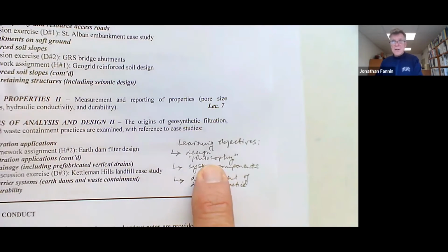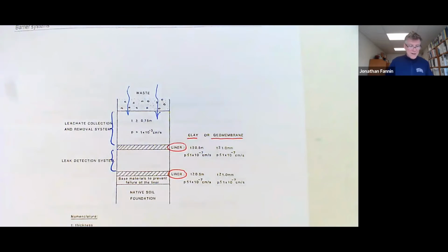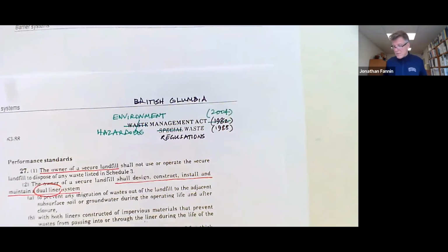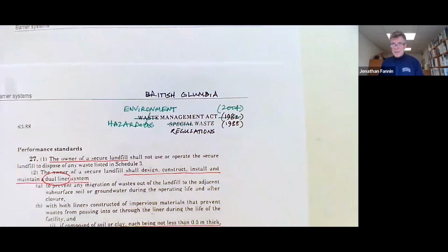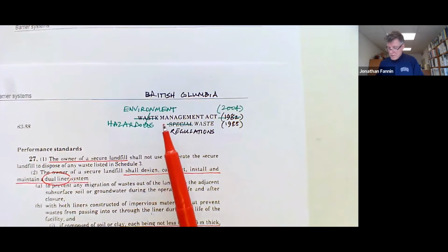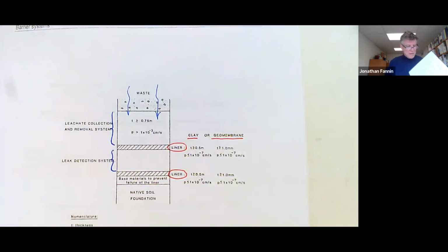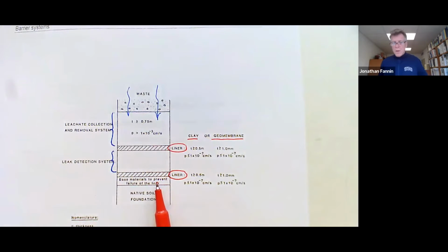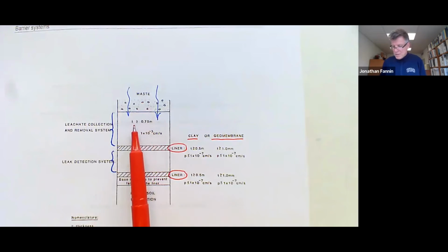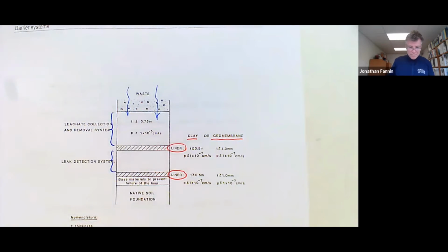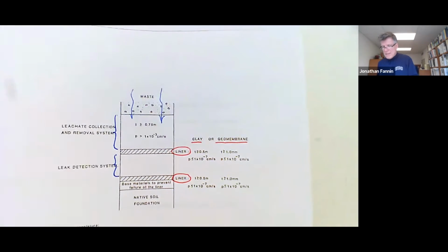There's a philosophy in terms of the objectives and the design philosophy, depending on the nature, depending on how aggressive or how hazardous, and there are criteria for what constitutes hazardous liquid by its biochemical, largely, properties. Then our philosophy is to have a dual liner system and an ability to determine whether or not the primary liner is leaking, and an ability to prevent mounding of leachate on top of the primary liner. And that's largely consistent, excuse me, with US EPA.